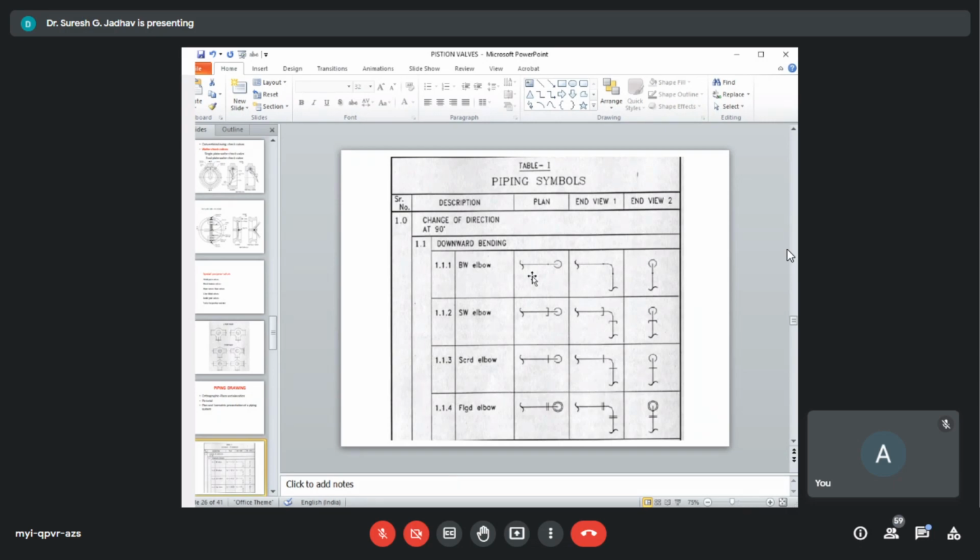Sometimes a preliminary piping study is made to fix the equipment coordinates. The other data required for the development of piping drawing are defined in the paper on equipment and piping layouts. For presentation of unit piping layout, the scales adopted are usually 1 to 25 or 1 to 33, and 1 to 100 for the pipe racks. We considered different kinds of scale in engineering drawing or engineering graphics. There are two types of scales.